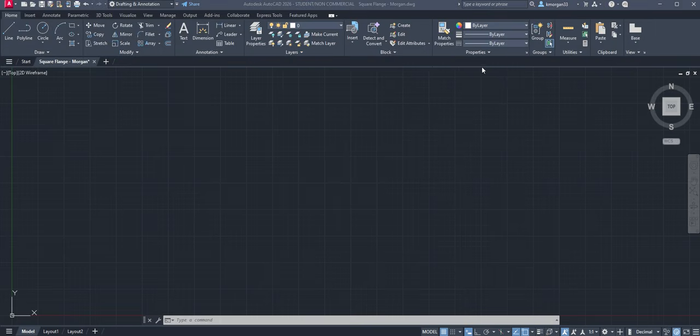After we have set and loaded the line types that we need, we are going to save it. Save the setting we just created. Of course, every time you do your drawing, make sure you save it. I usually prepare my drawings and I save like that. So I set my units, everything, and I save that file. So every time I want to draw something, I copy and clone the file that I set up, so I don't have to do reloading of the line types, okay. So that is up to you.